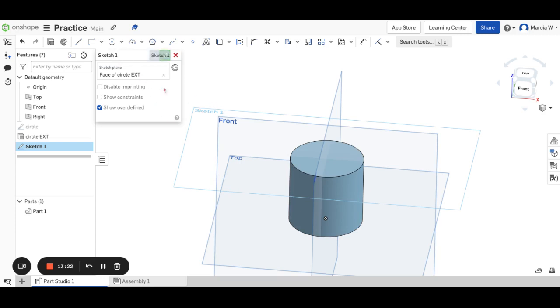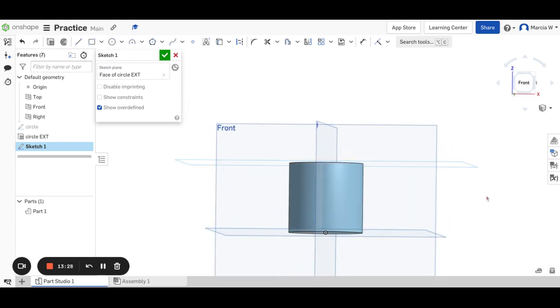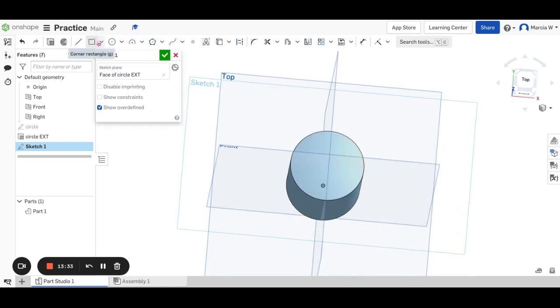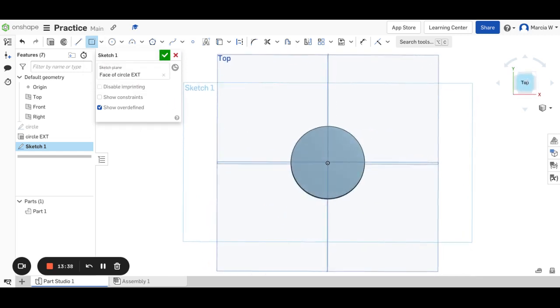And so you can see that this sketch corresponds with the name here. So if I rename it here, it's going to rename that here. You can see that it's on top of that pillar. So I'm creating a sketch on top of that pillar. Let's say I'm going to do a little center point rectangle. I'm going to view face down on the top. I picked center point, so again, it's going to go from the center. Let's drag that out, and let's say I want that to be 15 millimeters in that direction. So I'm going to constrain that to 15 millimeters in each direction.